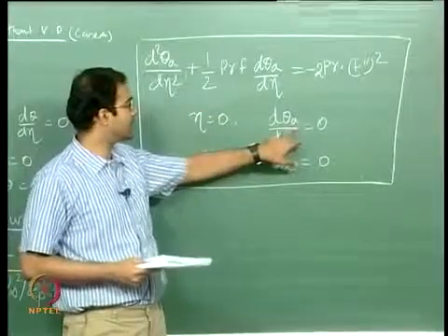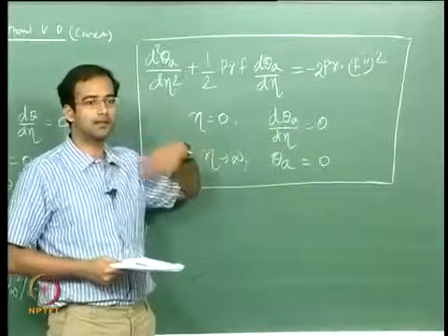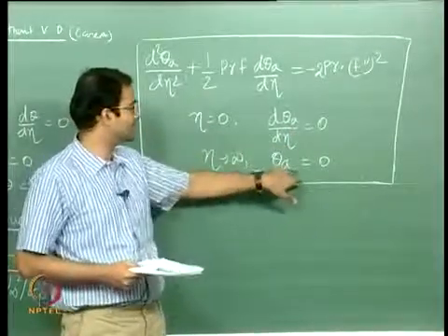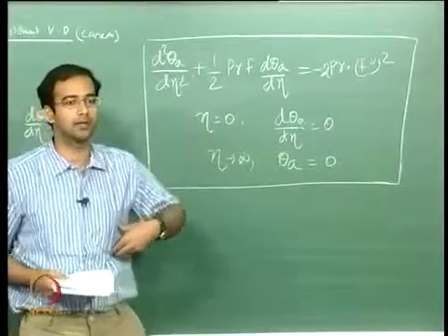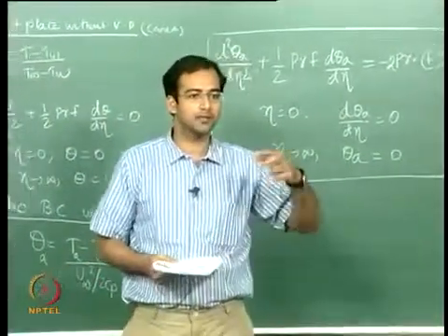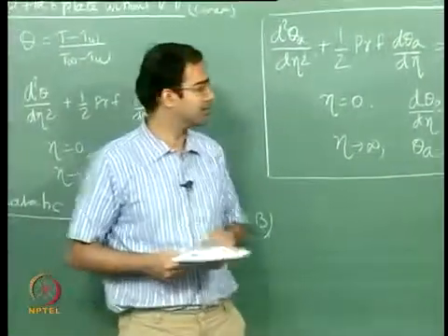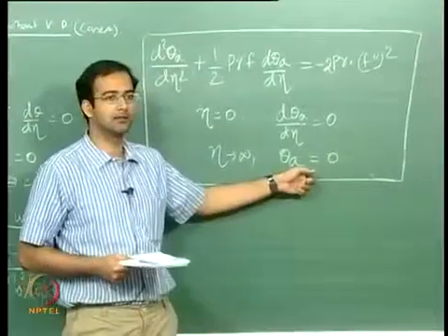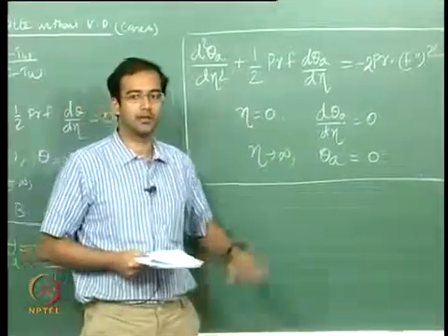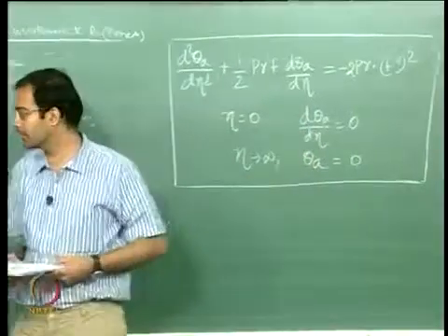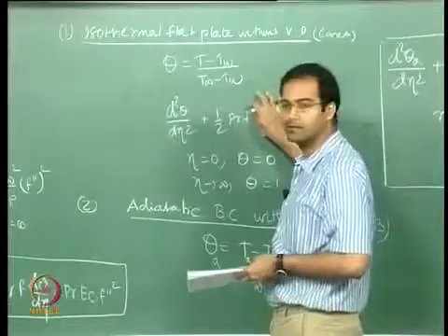You have the boundary condition for theta prime at eta equal to 0, so you can guess the value of theta at eta equal to 0 such that theta at some eta equal to 10 becomes 0. This is the other way of doing the guesswork, so that you match this condition, so you keep guessing the value of theta at eta equal to 0 here. Anyway, you can solve this problem by the shooting method. This problem already you have the solution by the shooting method.